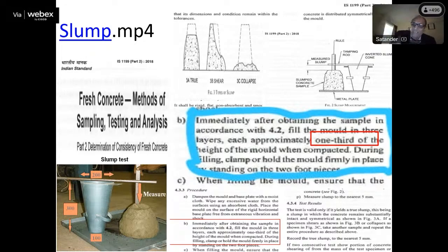He should put it in a vertical manner. So all these things come under quality assurance. The quality control person, whatever you say, will go inside and find the slump, three layers. Yes sir. So he will do. What is slump? When concrete comes down, the distance it comes down is the slump.